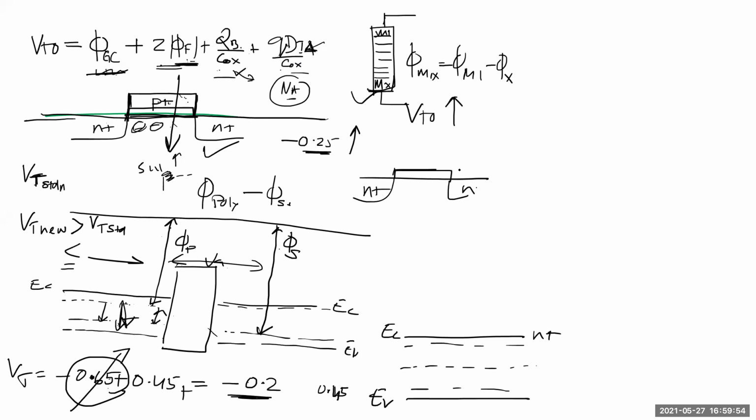Okay, but if you have a poly here, this is a P to P contact or N plus to P contact. Now you have a diode, right? So you have an N plus to P minus contact. So it's almost like you have a parasitic BJT basically. Well, first of all, if you do N plus here, you're almost all the time shorted here, but essentially it's just a diode, right? It's an N plus P minus diode.